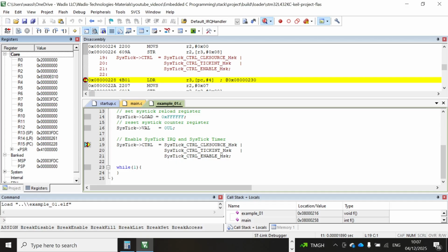By default, and after power on reset, the default stack pointer and stack area to be used will always be the main stack pointer. Therefore, the CPU stack pointer register will always be pointing to the main stack pointer. And hence, during the interrupt context switching, in our case, the CPU registers will be pushed to this active main stack pointer memory area.